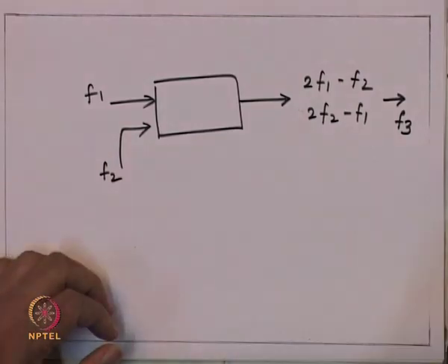So, the 4-wave mixing phenomena, if you look at it just from the interaction point of view, yes, it may create crosstalk between different channels, but the same phenomena when used more intelligently can be used as the frequency converter, which is used for wavelength routed networks for creating non-blocking systems.